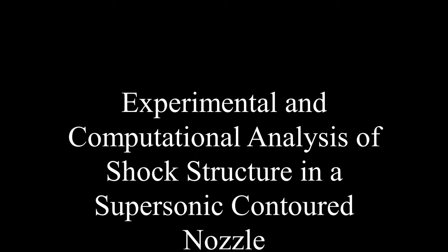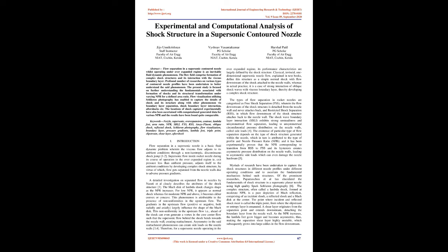Experimental and computational analysis of shock structure in a supersonic contoured nozzle. Abstract: Flow separation in a supersonic contoured nozzle whilst operating under overexpanded regime is an inevitable fluid dynamic phenomenon. The flow field comprises formation of complex shock structures and its interaction with the viscous boundary layer.